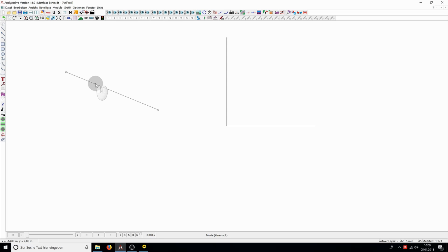You probably want to adjust several details of your graphic objects. This can be done in the same way for all graphic objects. Select them with the left mouse button so that their ends are marked with the selection icon, press the right mouse button and then on Settings. The quick key is the Enter key in this case.